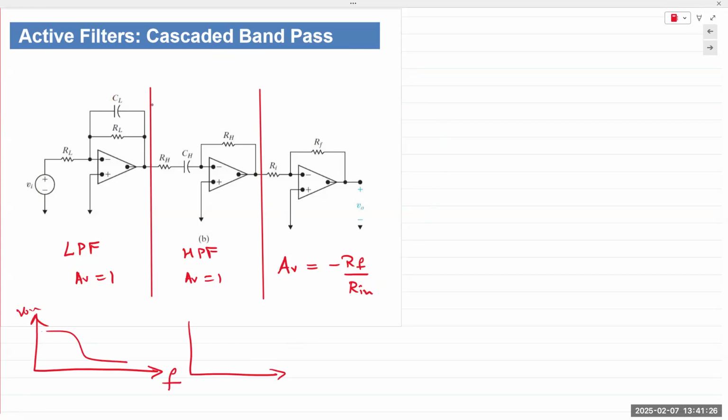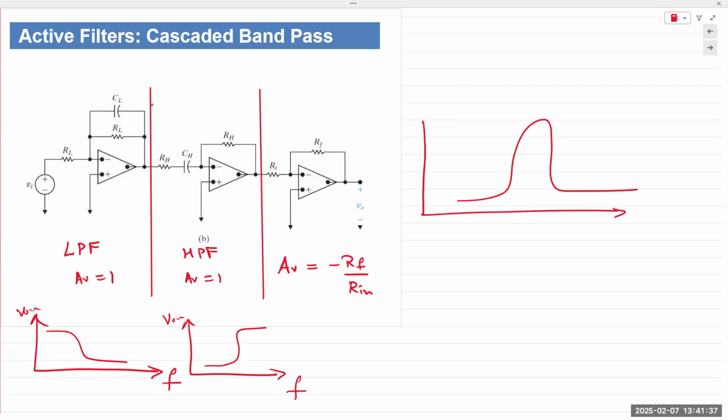A high pass filter allows high frequencies to pass through, and low frequencies are blocked. So at the output here, we obtain a band of frequencies that are allowed to pass through, whereas everything else is blocked. So a graphic equalizer is an electronic circuit that filters out certain frequencies and only allows certain frequencies to pass through. If you look at a graphic equalizer, whether it's a manual one or a digital one, it'll always state the range of frequencies for every single slider.